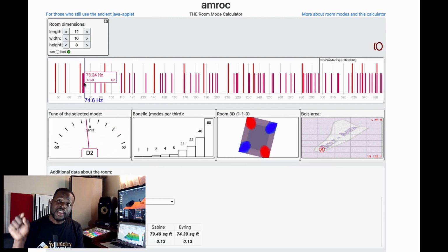They occur where the three walls meet, the corners where we have three walls, not really two. So if you understand this, then it becomes very easy to understand what goes on inside these small rooms, which make them so problematic. The strongest of all these room modes is the axial modes, which I talked about, the parallel surfaces, followed by the tangential across the 90 degrees, and then oblique, of course, where the three corners meet.